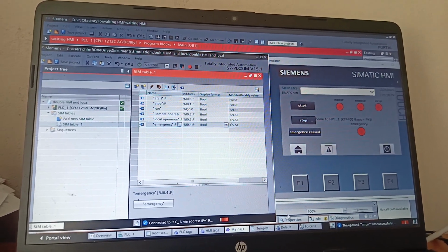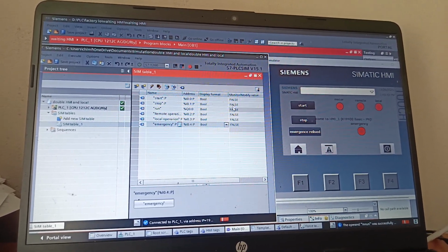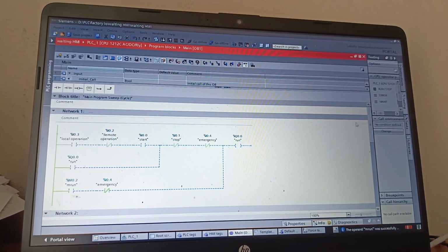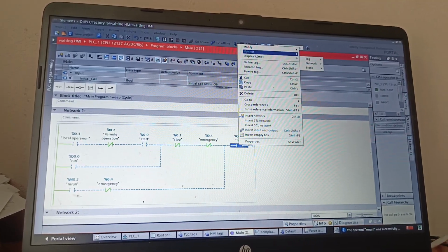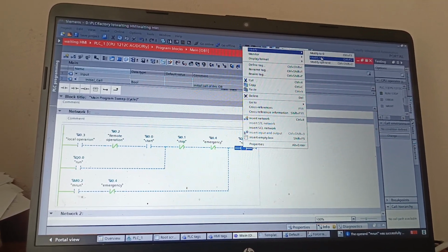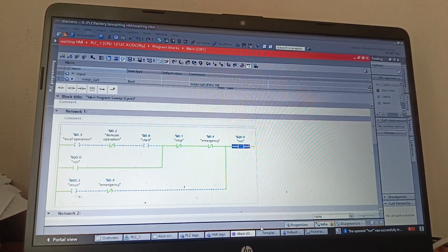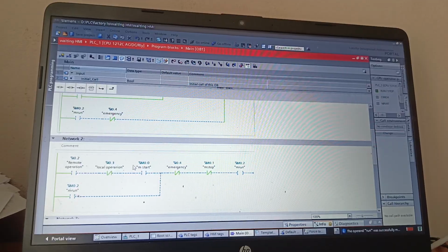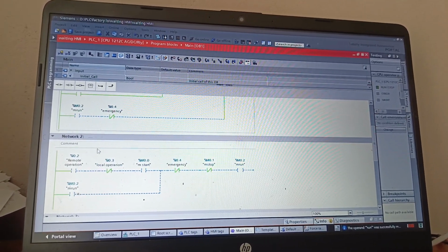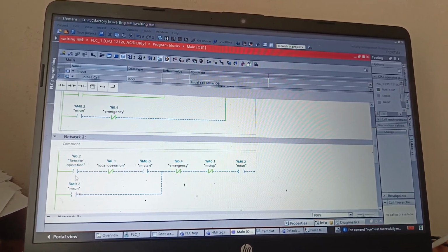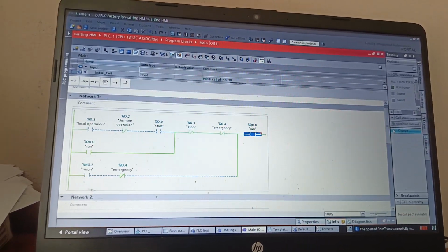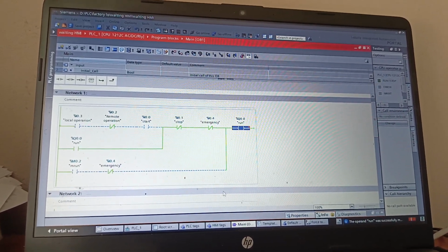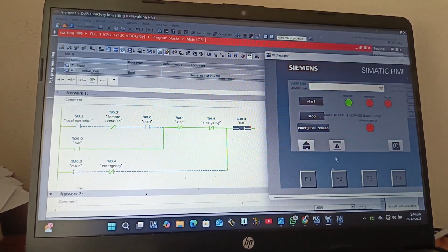See, they are local and remote. So if I say I run now, that was the local. Now if I run, that was the remote. If I run the local side of it, I modify this one to 0 or to 1. Sorry, it will run, meaning this one, which is the remote, can't run because the selection is on local. But for now, that can be viewed once everything is wired. So once I run this, it will still indicate the motor is running.